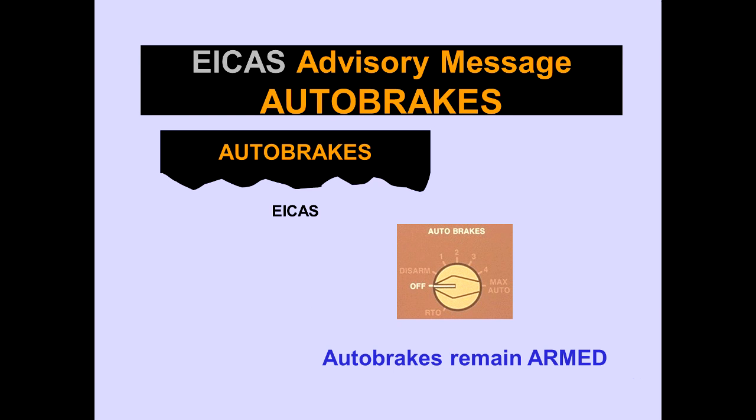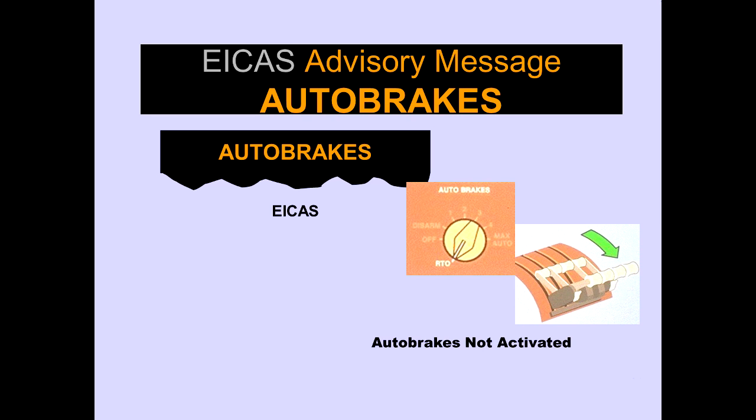The EICAS advisory message AUTOBRAKES is displayed if auto brakes remain armed when selected off. The EICAS advisory message AUTOBRAKES is displayed when a rejected takeoff is initiated and auto brakes have not activated. The Autobrake Selector remains in RTO.